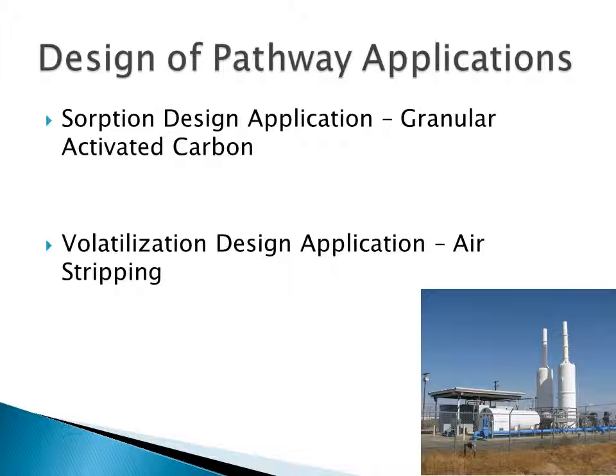Hazardous chemicals that have a tendency to partition onto soils may also be effectively removed from aqueous solutions, such as groundwater or dilute recreational wastes, by sorption and ion exchange processes. One of the most common engineered sorption systems for the treatment of organic contaminants is granular activated carbon. GAC is a high surface area sorbent commonly prepared from natural carbonaceous materials.